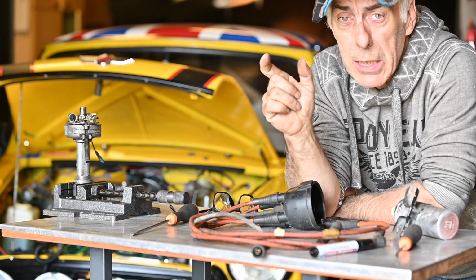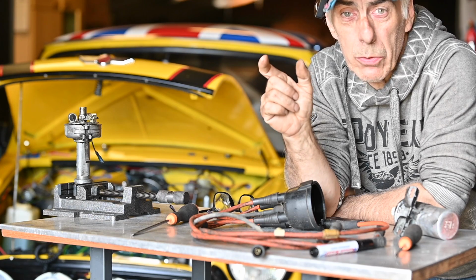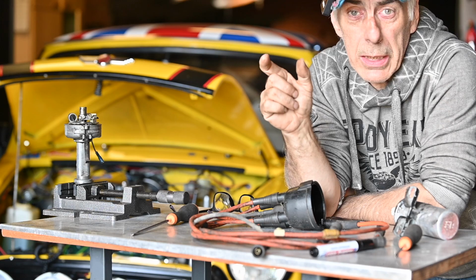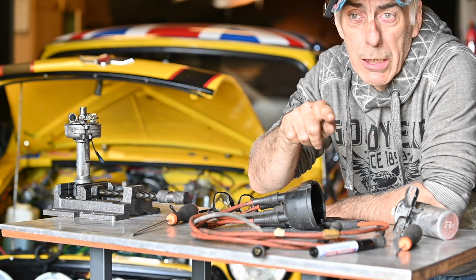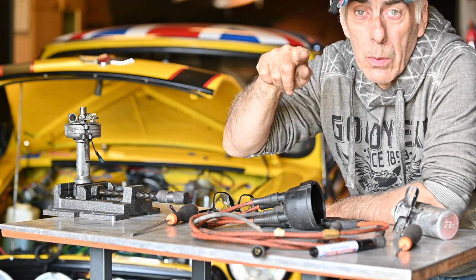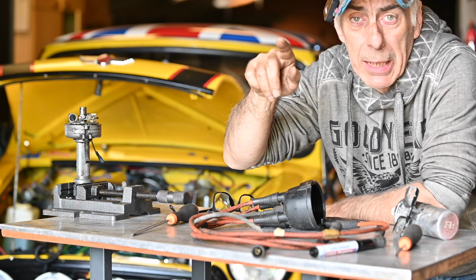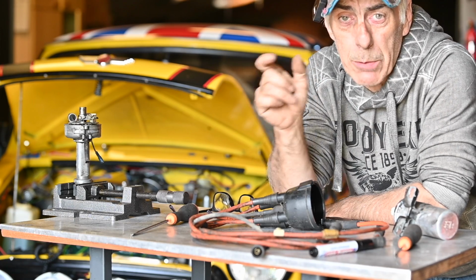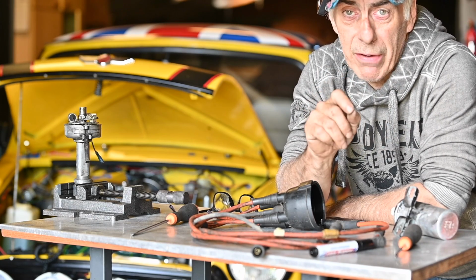So that actually means with a running engine, we might have to advance the spark. We want to have the spark ignite that mixture prior to the piston hitting top dead center. So by the time that the fuel burning, that explosion, starts to creep up and hits its peak, we will have the piston just on top of the top dead center, and then we can push it down violently with all the power that we have left in that explosion. And that is so critical. That's why we need to have advance.